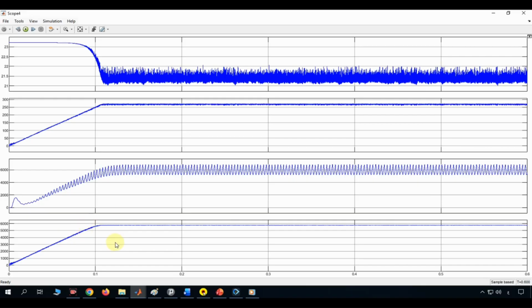This kind of behavior, a clean startup transient followed by a steady, ripple-carrying operating point, is exactly what you'd expect from a maximum power point tracking system settling onto its target after the simulation begins, with the switching ripple you'd expect from any converter-based power electronics running continuously afterward.